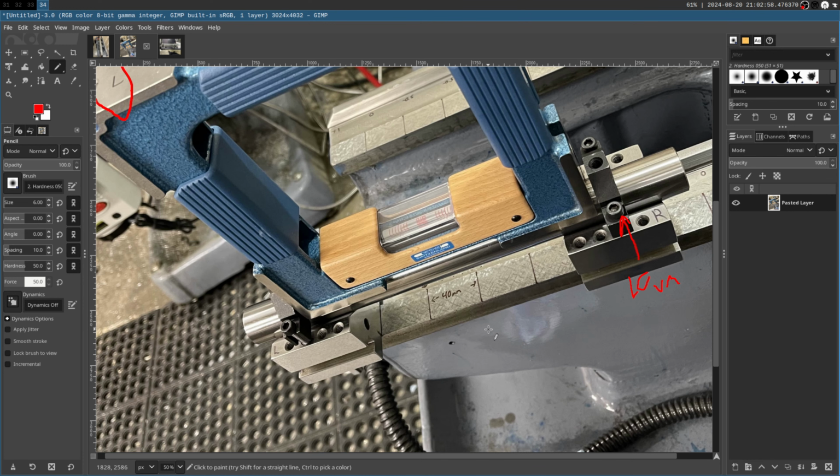That is what I have decided I am comfortable taking these measurements as. I look at the bubble, and I take a reading to the nearest 0.5. So if I feel like it's mainly splitting between 2, I'll call it 0.5. If it's closer to a line, I'll call it that line. Obviously, that means the error in my readings is approximately 5 micron, which is fantastic, because I know that this lathe is not flat to 5 micron. That would be basically factory spec.